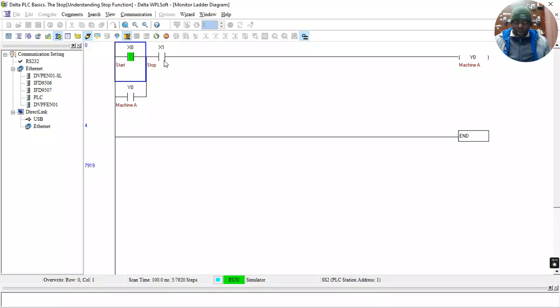When we program our part we simulate and we're done, now we have to load it to the PLC. We have to change that stop to a what? To a normally open. Why? Because the push button, every input that is going to be normally closed would have to be what? Would have to be programmed opposite. All right, because that normally open would energize and therefore defeat the effort, defeat what we set out to do. So bear that in mind. It will be clearer, perhaps, when you do the actual practice.